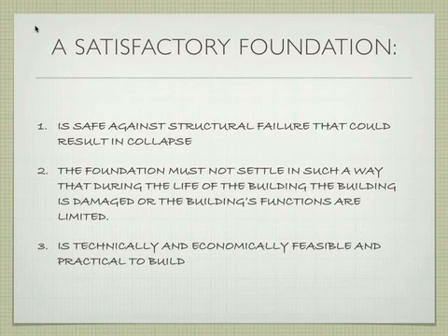The next thing is that a foundation shouldn't settle in a way such that the building becomes unusable, or parts of it don't settle correctly compared to other parts, so you end up with cockeyed door frames and that sort of thing. So a foundation wants to keep the building relatively level, and allow it to still maintain its basic functions. Because if it doesn't do that, then obviously the foundation has failed to the point where you can't use the building, which defeats the purpose of having the building in the first place.